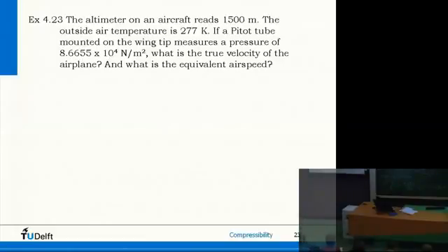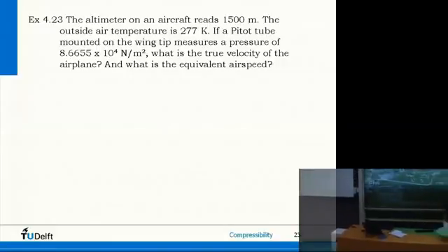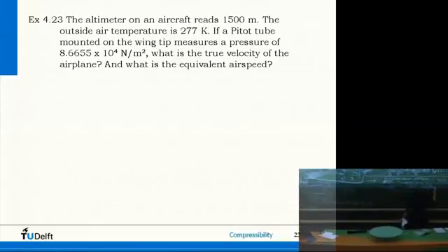Does the pitot tube just measure the static pressure or the difference between them both? No, so a question of the definitions, good point. A pitot tube always measures total pressure. So the pitot tube is this one, total pressure. This is the pitot static tube. So this one is called a pitot static tube. So the pitot tube measures total pressure.